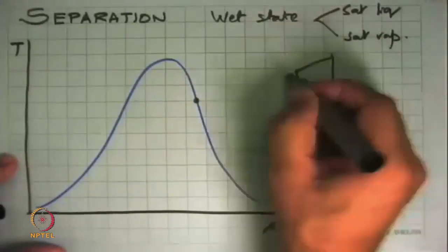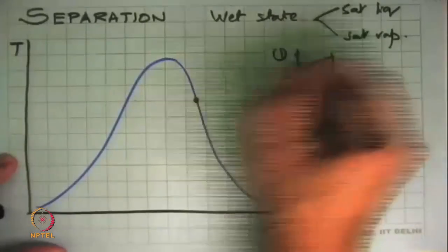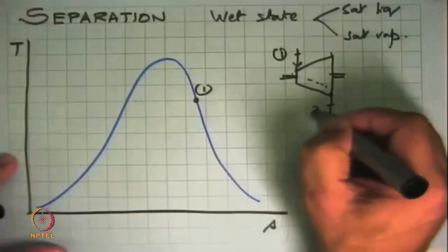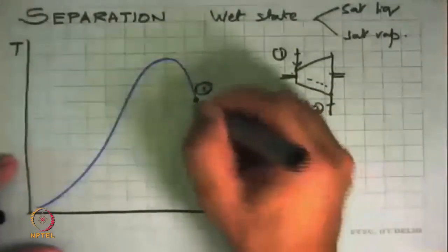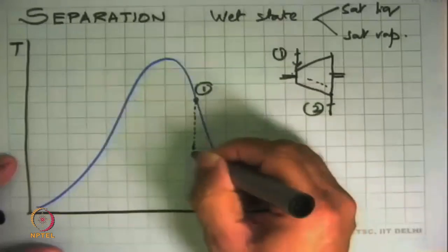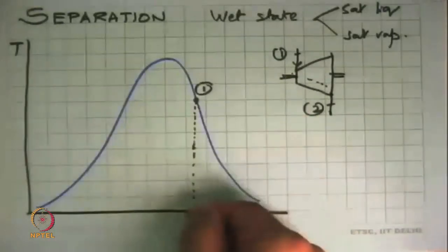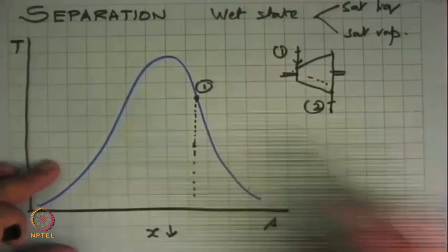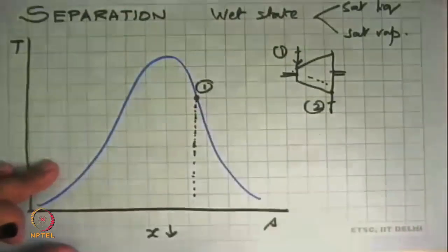So say this is the turbine. There is a shaft which is producing power. We got state 1 over there, and we allow the steam to expand in this, and we take it out at state 2. Now what happens here is that because it is dry saturated, the states in which the turbine will expand will all be along a line which is like this. And as you keep going down, the dryness fraction keeps getting worse, from 0.99, 0.98, 0.9, 0.8, 0.7, 0.6, something like that.